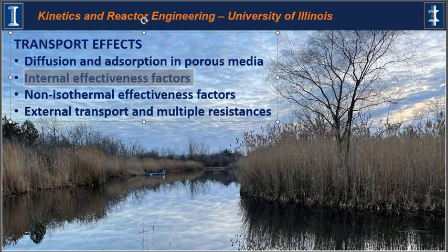So the overall rate may actually be limited by external transport, by internal transport, or by the rate of surface reactions. And in some cases, the overall rate may even be influenced by the transfer of heat into or out of the support pellets. So we're going to consider cases where we have thermal equilibrium right now. We're going to focus on the internal resistances, diffusion into the porous support material. So these are internal effectiveness factors in this video.